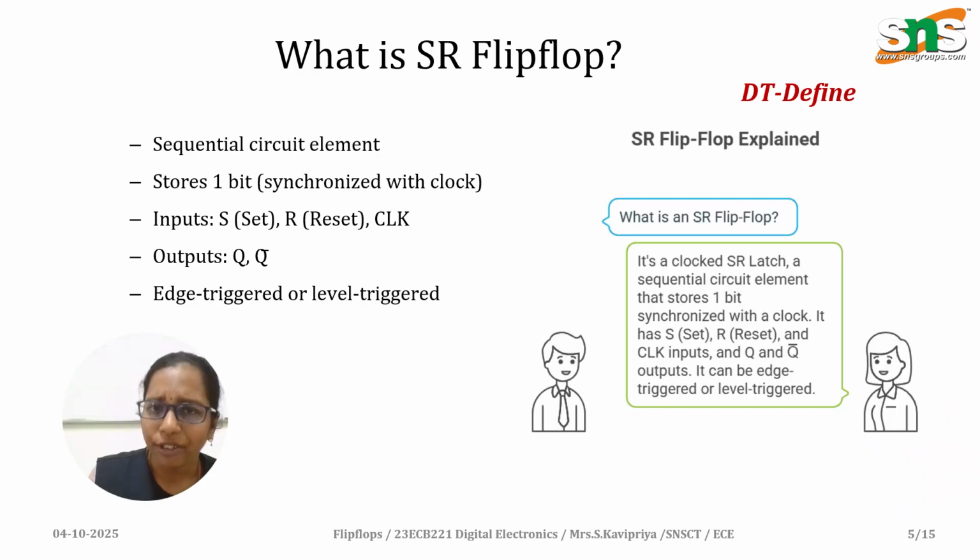What is an SR flip-flop? An SR flip-flop is basically an SR latch, but it is synchronized with the clock pulse. It has inputs S and R, which are nothing but set and reset, and outputs Q and Q bar. It is capable of storing a single bit of information, and it is a sequential circuit element, where a latch is an asynchronous sequential circuit and a flip-flop is a synchronous sequential circuit. It can be edge triggered or level triggered.